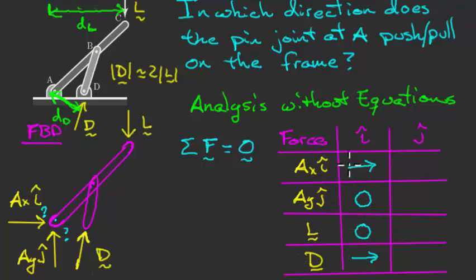Right, 0, 0, right. And if I take right, add 2 zeros, and add another right to it, this ends up being right. Yeah, but it has to end up being 0. I can't have a net force to the right. So again, I know this one goes to the right. So the AX, that's the one that had the question mark next to it. The AX actually has to go the other way in order to have equilibrium. So I've got this thing wrong again.